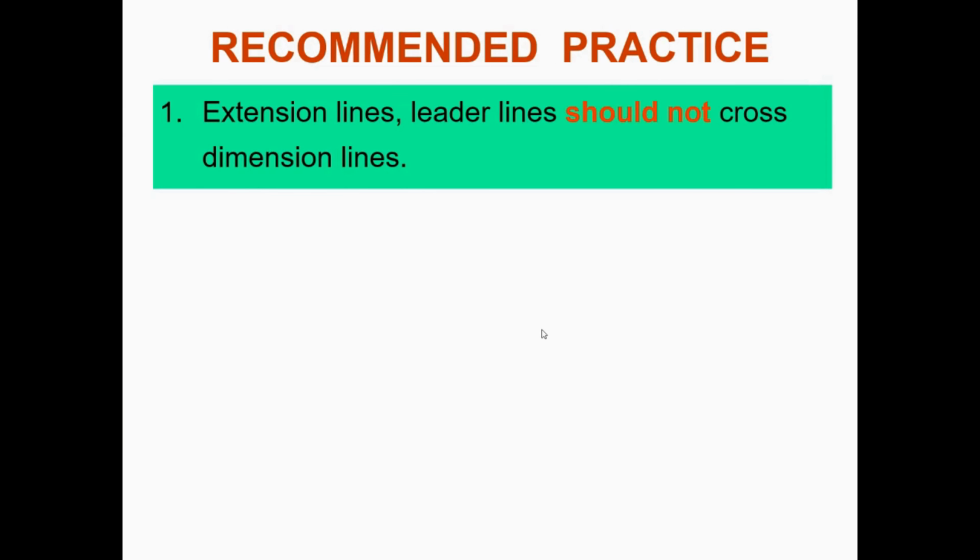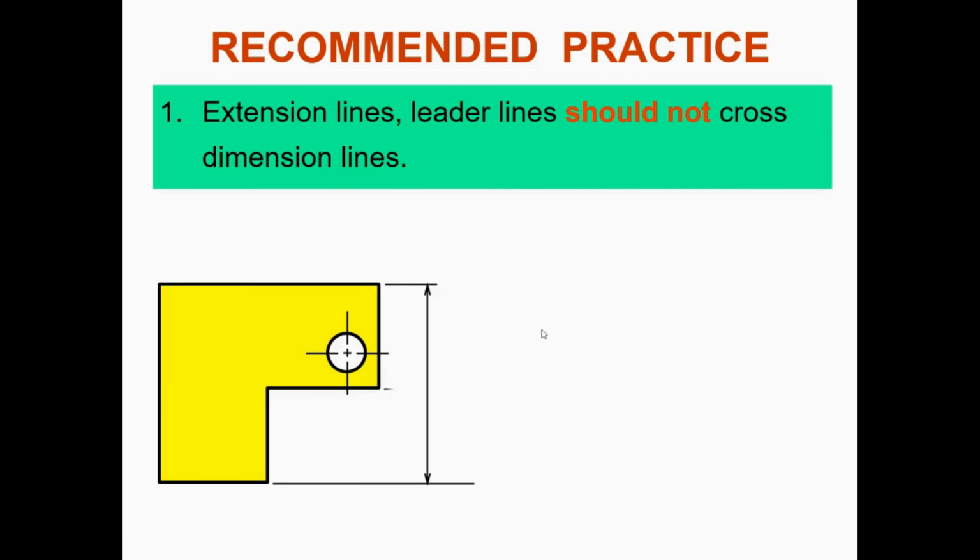Extension lines, leader lines should not cross dimension lines. So always make sure that the extension line is not crossing. In this orientation, we have the extension line crossing the dimension line, and it's a very wrong practice to do. Leader lines should also not cross the dimension line.